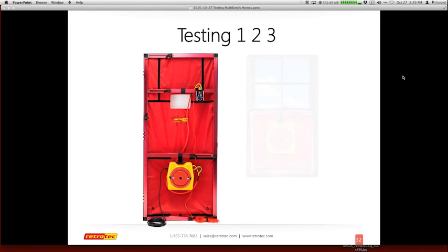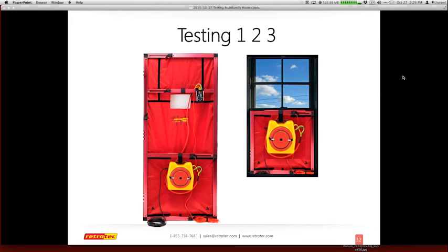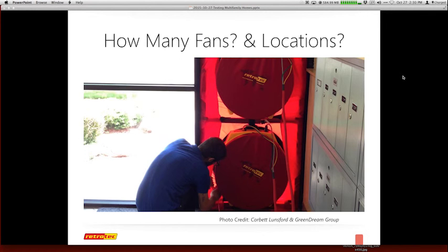So these are some smaller ways to actually isolate units that are adjacent. Sometimes you can just get away with a duct tester, or maybe even a duct tester in the window. So on the right is actually the Passive House frame and cloth that Retrotec now has to do a duct tester test as a blower door method.